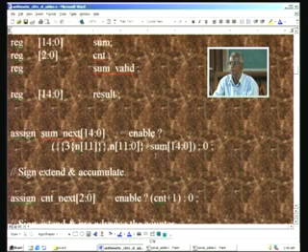So, to start with, we should not forget to clear this sum, otherwise we will be adding an unwanted number, and therefore 0 plus n naught will be n naught, and this will be assigned to the sum next, and this will be registered only with the arriving positive edge of the clock subsequent to this. When enable is not high, actually 0 goes through the sum next.